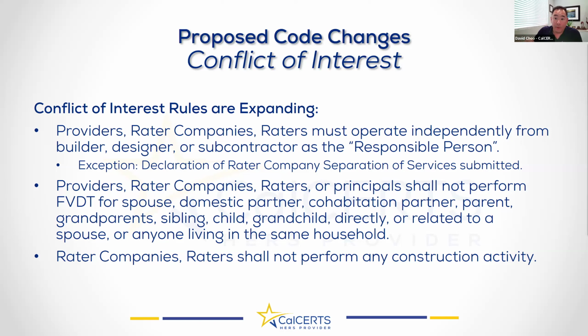Now, the third bullet point, that's always been the rule. To clarify, it says that a rater can't perform construction activity. That includes fixing ducts, sealing boots, adding refrigerant to the systems. They're not supposed to do that. So if you as a code official come across this, please let the providers know, because we need to have a conversation.